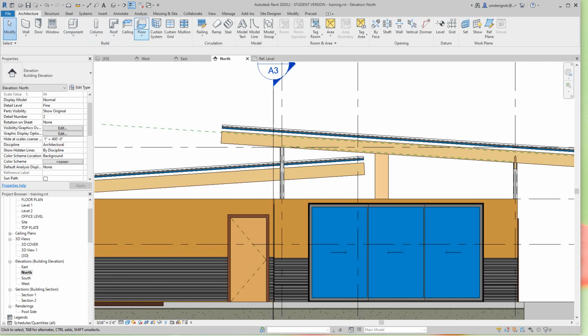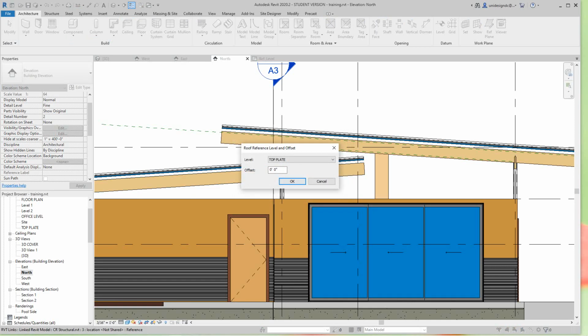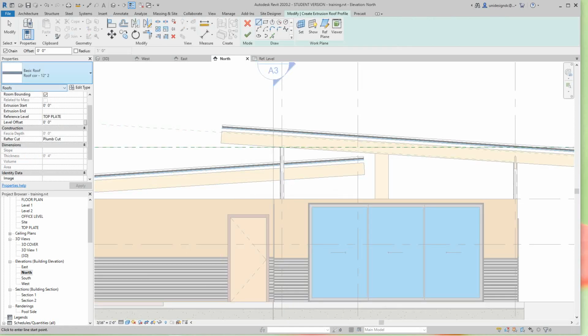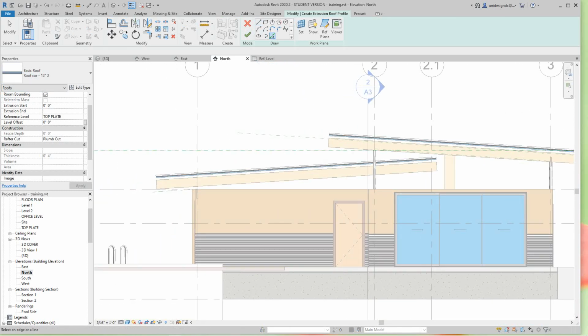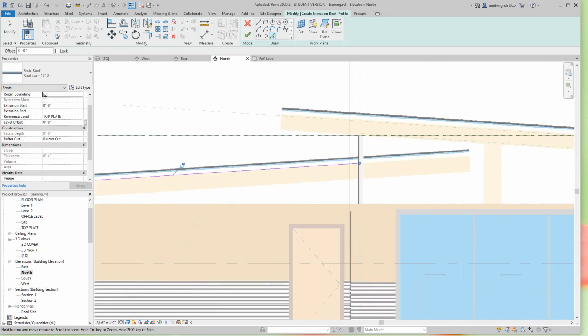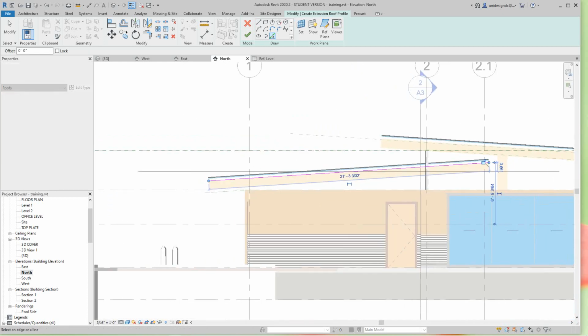And it'll select roof by footprint. I'm sorry, by extrusion. And we'll pick this plane. Okay. And now I got this 2-inch in here, so that'll work. It's nice. It should fit under there. It could have made it 3. Pick this line here. Drag this through. And I'll finish.